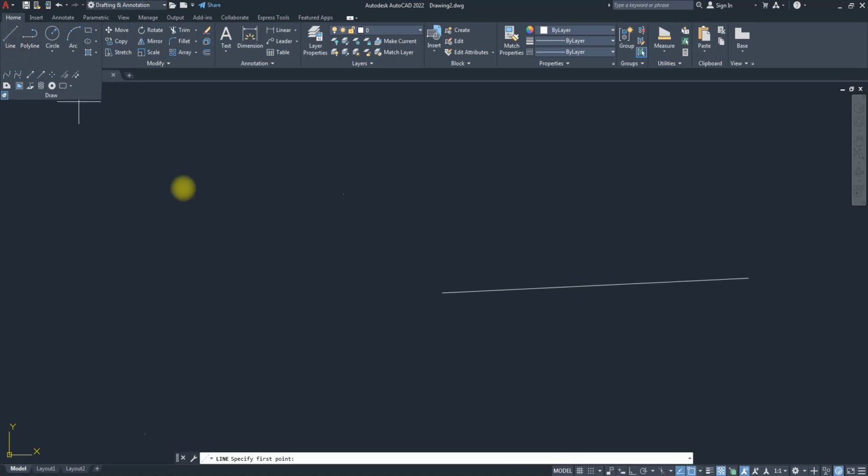So I can actually snap to those points. You notice if you want to snap to a point, the object snap type you see is node. So that means you want to look out for node. If I come here, this is node. That means this is one subdivision. And that's how you know those things.